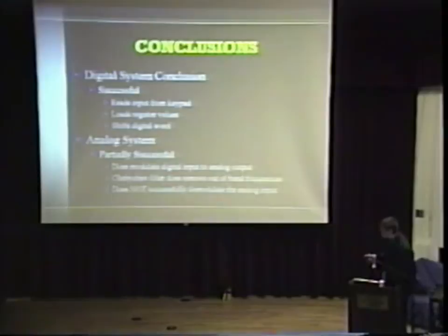For conclusions, the digital system was successful. I can read an input from the keypad, load the correct register values, and shift out the bits. The analog system is partially successful. It does modulate the digital input, and the filtering successfully removes all out-of-band frequencies. The issue still remains that it cannot successfully demodulate to digital values.